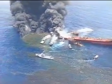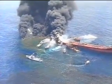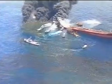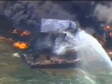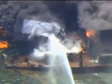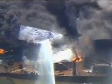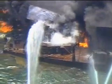Tank ships transporting flammable or combustible liquid cargoes in bulk have special considerations, not only because of the potential dangers involved with liquid cargo vapors, but also because rapid decision-making and action are essential in the event a fire does occur. Again, the vapors from the liquids are the primary concern. It's the vapors that burn, not the liquid.